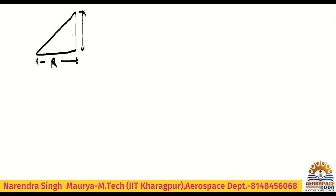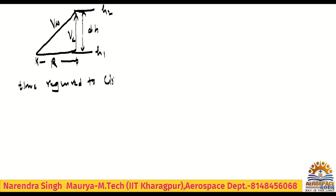If this altitude is h1 and here it is h2, then this altitude is dh, this velocity component is Vc, and this is V infinity. So what is the time required to climb from h1 to h2?